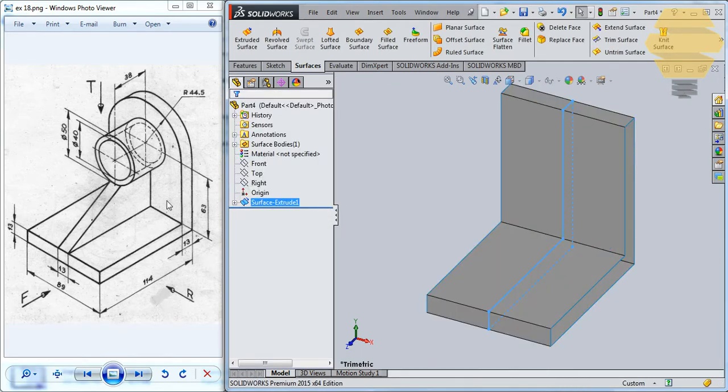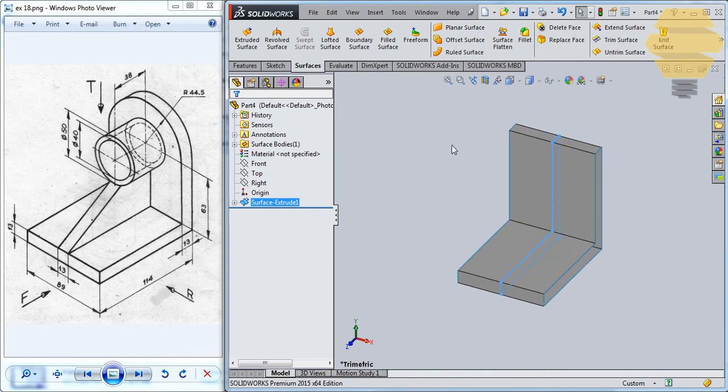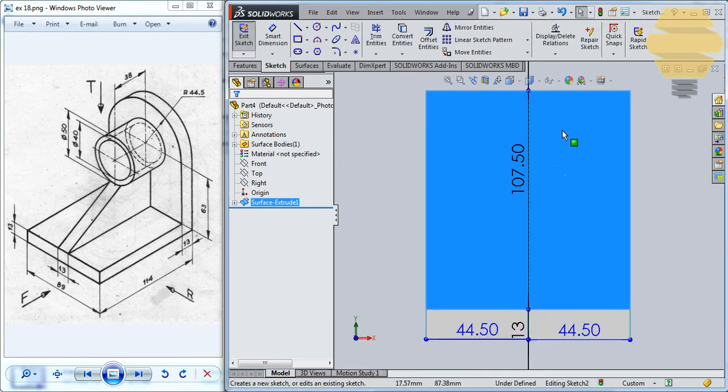In this case I have preferred to give it on both sides because once we create it this way, then I don't need to go and search where is the center point for creating the cylinder. I already have the center point because there is an XY plane over here. There is an origin system over here, an axis system.